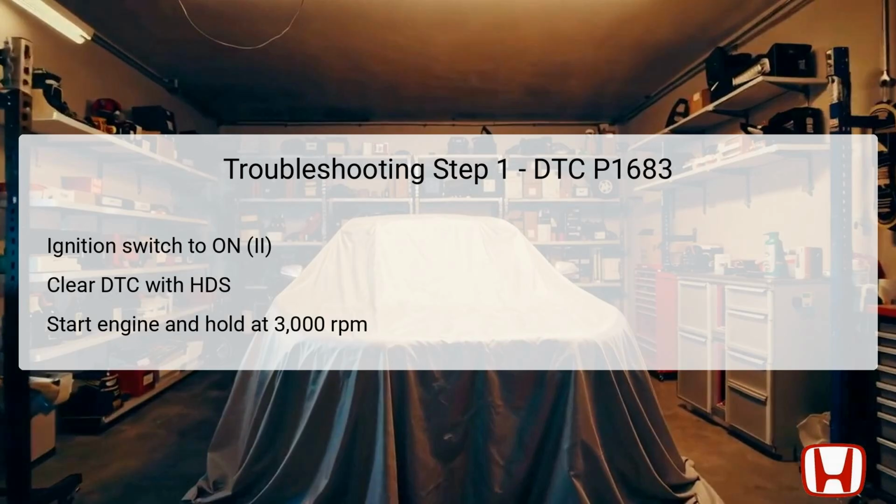Once the fan has engaged, let the engine idle. Then proceed to turn the ignition off and wait for approximately 10 seconds. This reset allows for a fresh system check before proceeding to the next diagnostic phase.